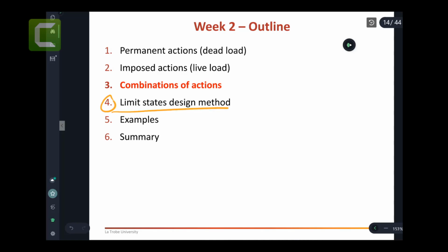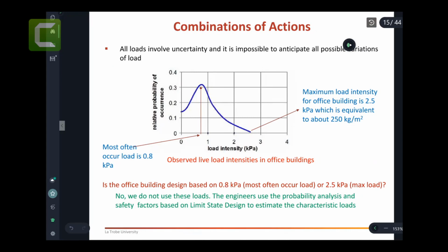The other section is going to talk about the limit state method, which is again just preparing you for what's going to happen in the design, which starts in week 4 after the wind loads. It's a limit state design. Simply, we're going to compare actions with the strength by considering the standards' recipes, which are the combinations, etc. So talking about combinations, just a quick story before I show you what those combinations are. Combinations are the safety factors, which we have to apply to dead load or live load. All right. Now, here we have a quick story telling us why people decided on those factors.